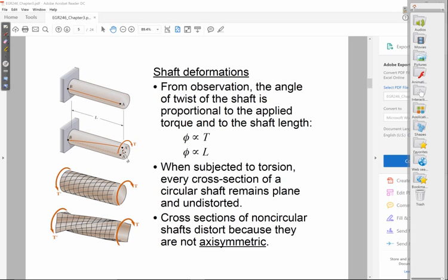What you can see is that the circular shaft does not warp. Okay? I look at every single cross-section on that shaft, and each cross-section remains circular even after I twist on it. In the rectangular shaft, it's pretty obvious that the cross-sections are no longer rectangular. The whole shaft, you can see, warps. And the very fact that it warps means that stresses and strains are going to be distributed in a very complicated manner throughout this shaft, okay? And that makes it very difficult to analyze.